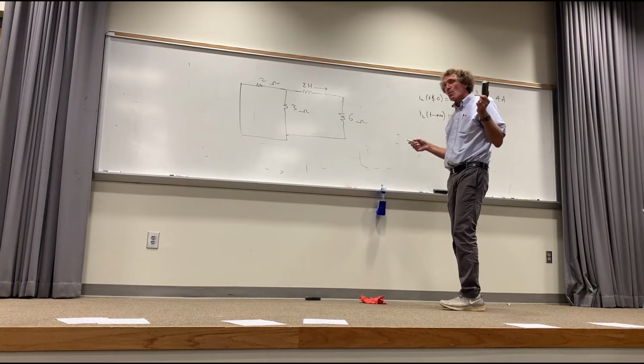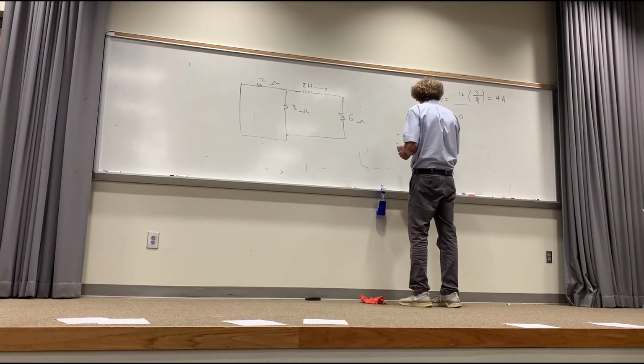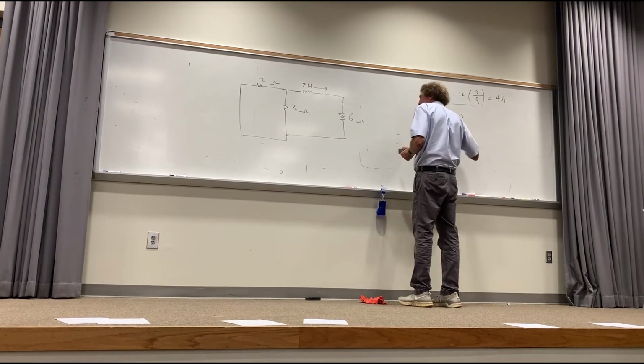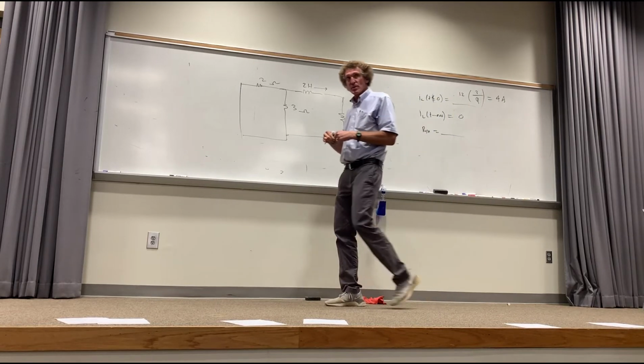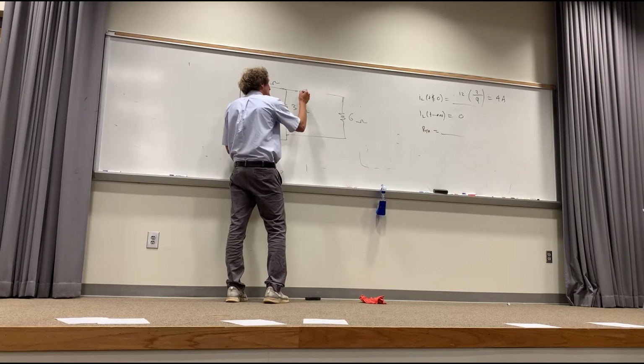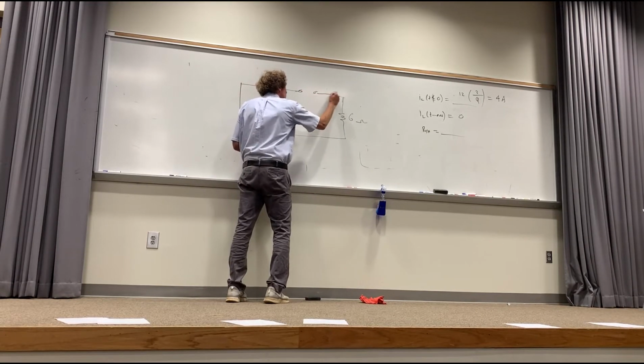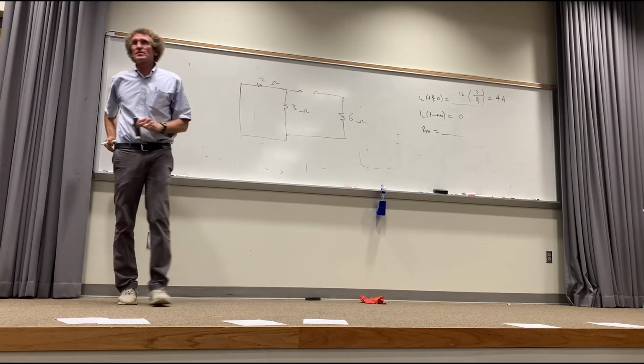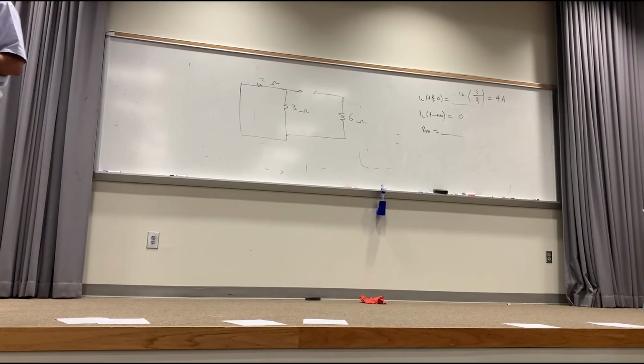All right, now we need the resistance, R Thevenin. Correct, class? For R Thevenin, this is important to see. I'm going to erase that inductor and just put in some dangling leads. I want the resistance between those 2 terminals. I literally rip the inductor out. I want the resistance across the inductor. Follow me? Well, what's it going to be?